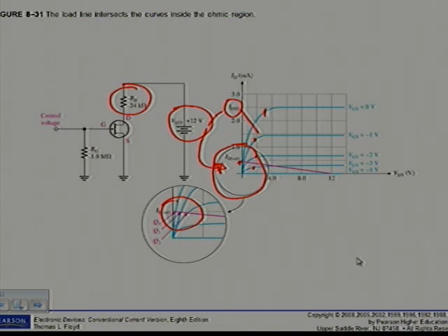So then it shows the operating region expands, with the Q points there, enlarged here, Q0, Q1, and Q2. So as you move along the load line in the Ohmic region, the value of RDS varies as the Q point falls successively in curves with different slopes.